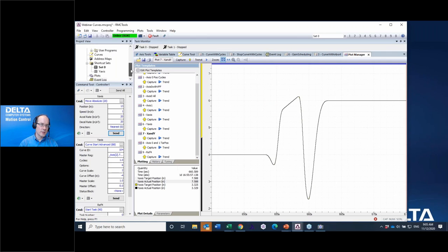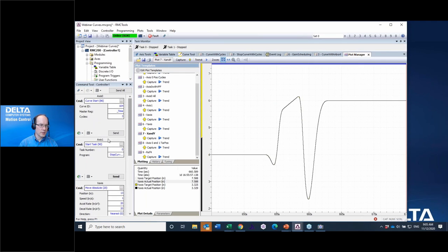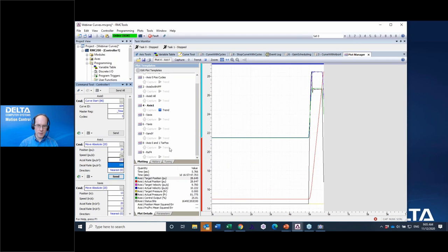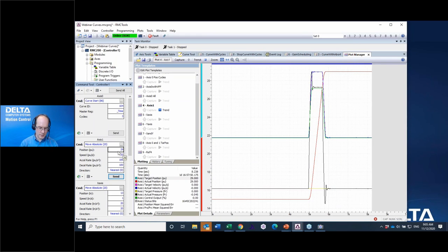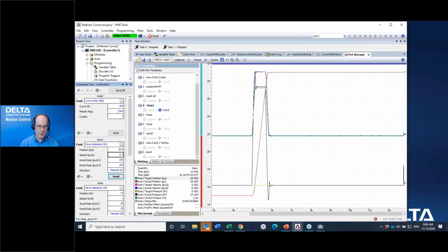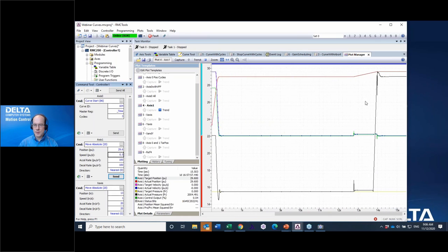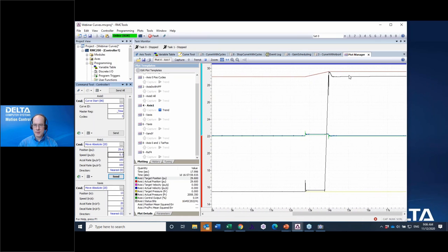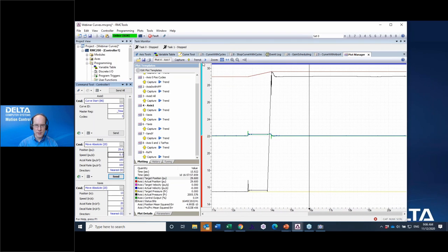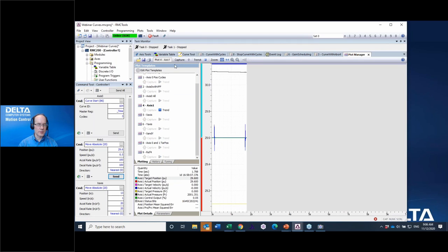We have an axis. I think axis 1 maybe is in pressure control. So let's go move that here. Let's see, axis 1. If we move to 29, I think we start reaching some pressure there. Let's see, I'll move to 29.6, move there a little bit slowly. Okay, so we see we're in pressure. The black line is the actual pressure. It's simulating a spring between 29.5 and 30 inches. So we can see our forces right there.